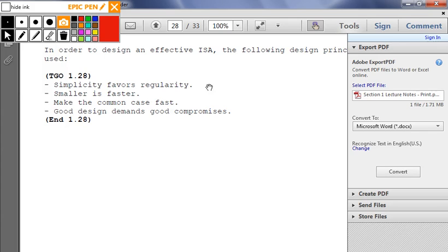But there are other things, and we're going to be going a little later when we start going into VHDL about the difference between structural and behavioral coding. The difference is that structural coding requires a lot more code, but the result is it's simpler for the synthesis tool to make, so the circuit will be smaller, it will require less power, and you'll be able to operate it on more, especially when you're putting it onto a Virtex or a Nexys board.